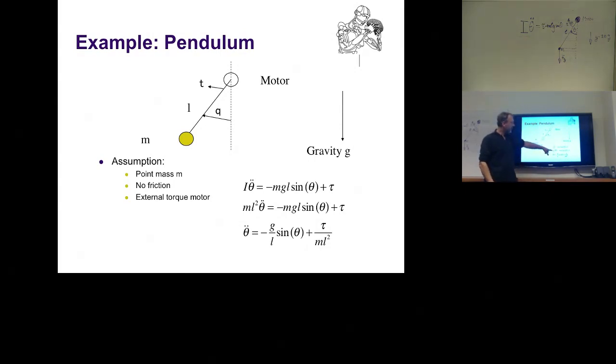Next thing, let's see whether we can simplify the inertia of a point mass. That's the reason why we made it a point mass, because it's so simple. The inertia of a point mass I is simply the mass times the distance squared relative to the rotation point. So here's a mass, it rotates about this point with distance L, so ML squared is the inertia of a point mass. Good, and so we can actually insert this here. Beauty about a whiteboard, I can erase stuff and just write ML squared here. And now we have, in this equation, everything we wanted to express.